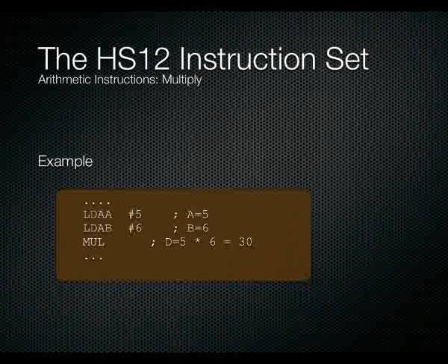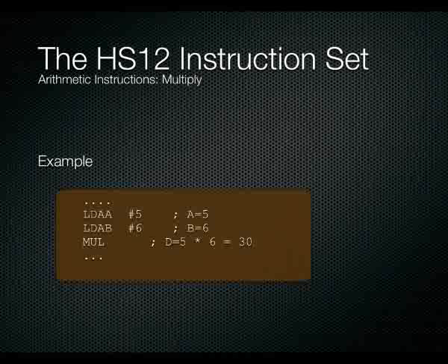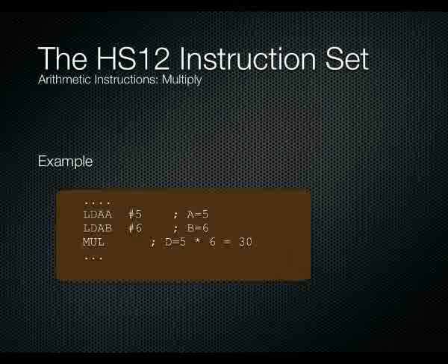But be aware, the multiplication command is a very costly command. It will take about 8 to 10 instruction cycles to do it properly. So it's not a command you want to use a lot. If you're doing a multiplication by 2, 4, 8, or 16, something that's a power of 2, it's probably easier to just do left shifts instead of actually doing multiplications, because left shifts are a lot computationally cheaper than doing multiplication. So it depends on what sort of numbers you're multiplying. If you know beforehand that it's a factor of 2, then simply do left shifts. If you don't know, then of course you're limited to using the multiply commands.